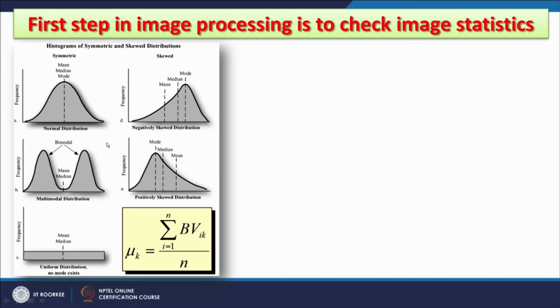These things I have already discussed when we discussed why to use histograms, and in that discussion we saw that it is very rare to get a normal distribution in satellite data. Sometimes we get a negatively skewed distribution because some land features may have high pixel values, maybe like in a desert area or snow covered areas in a hilly region. You may have a bimodal distribution.